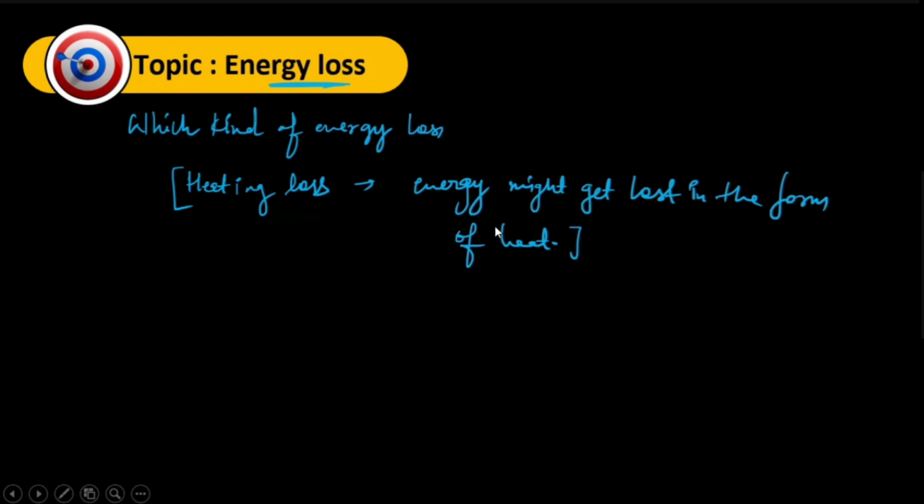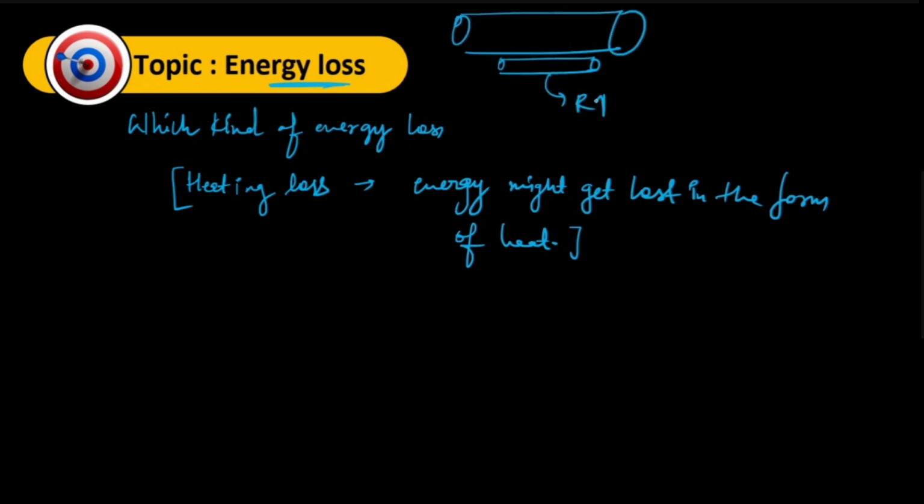Earlier, we were using lighter diameter wire for transporting electricity. If it has a lesser diameter or lesser area, it would be of more resistance. And if it's a bigger diameter, it would be of less resistance. If it has more resistance, it would heat more, whereas the bigger diameter wire heats less.